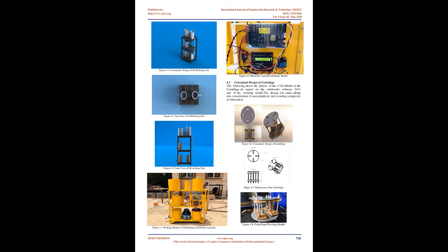Conclusion. From the results of the experiment obtained, used engine oil can be regenerated on a bench scale at controlled conditions. It showed a better quality of regenerated oil using industrial bleaching earth, with a viscosity at 40°C, specific gravity, and total acid numbers so close to that of the standard grade.